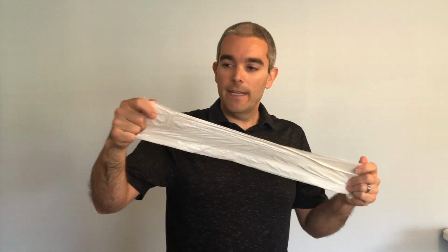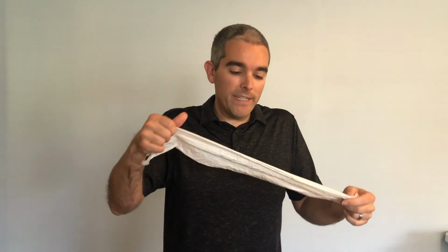So instead of picking up maybe only 0.02 inches of deflection at the connection, over the entire member now we're picking up 3, 4, 5, 10 inches of deflection, whatever it happens to be. We're picking up a lot, and we can't use that member anymore in design when it changes geometry by that much. So that's why we check yielding for the gross section, but then we only look at fracture at the net section.